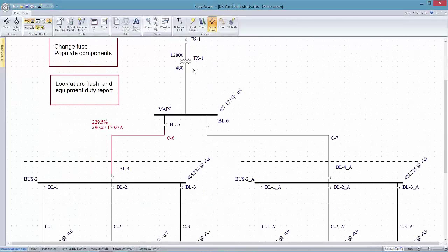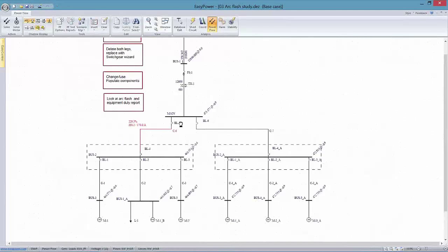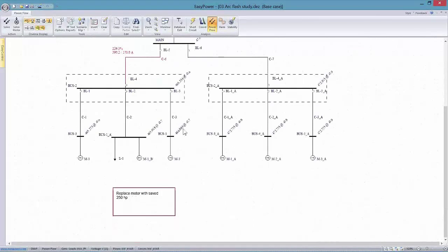Two ways to kind of mitigate that is either reduce your power load or add power factor correction. Power factor correction is a matter of adding some capacitance to the system, and in part its other benefit of adding capacitors is to raise the voltage on a particular bus.